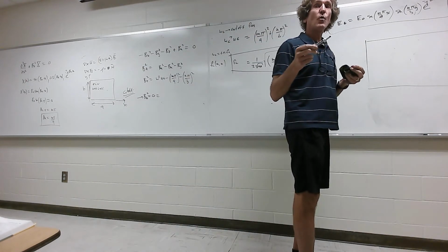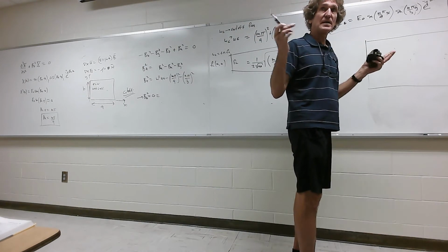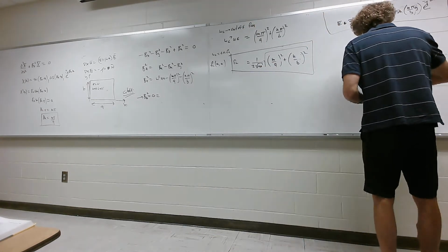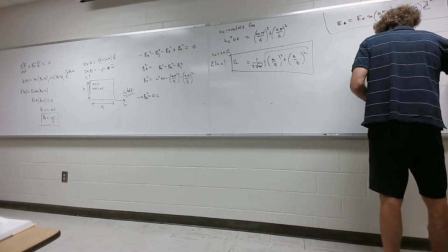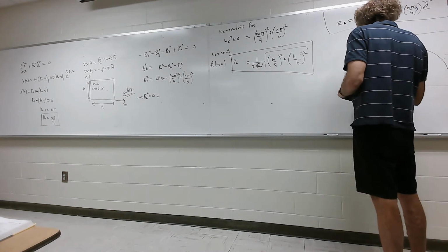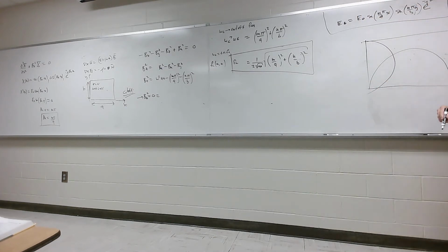When you have a 1-1 mode, if you looked at the intensity of the electric field, you'd see a sine wave showing the proportional magnitude of the E field as you move in the x direction, and you would get a sine wave the other way too. That would be the 1-1 modal pattern in the two directions.